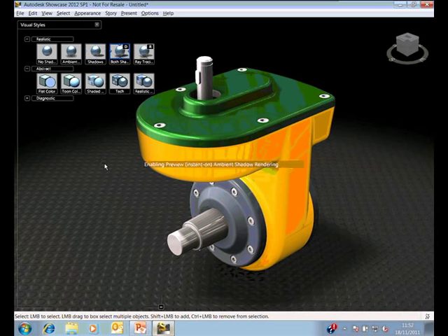If you want very, very high quality single rendered images, then use ray tracing. I'm not going to run it now. It takes about a minute to run through. Don't move your model while you're ray tracing, because ray tracing just takes a shot of what you've got on the screen and works on that. As soon as you move the model, it'll start the ray tracing again. But ray tracing will give you a very, very high quality image that you can export out to whatever file format you require. There are also abstract finishes you can add.